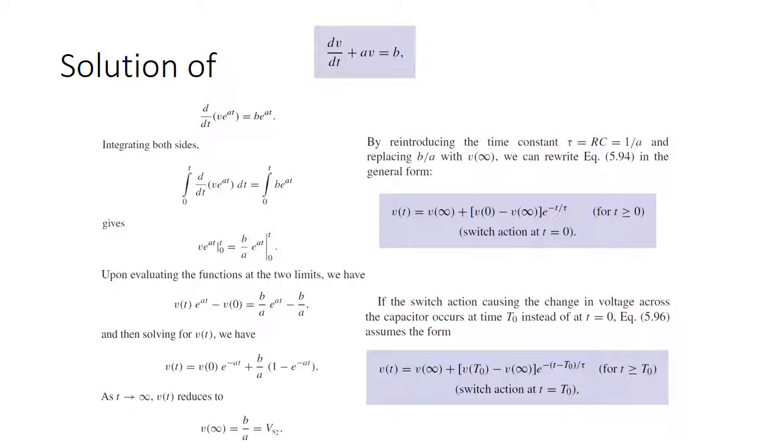At a very long period of time, whatever your voltage is in the second source, your circuit is essentially going to tune to that second voltage. And that's easy to make sense of too, because the capacitor either discharges backwards or fills up if it's going from a smaller voltage to a bigger voltage source, and you're going to eventually get it to saturate.